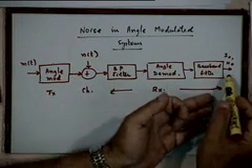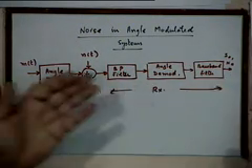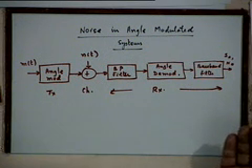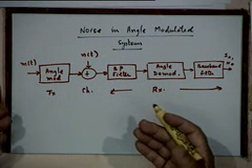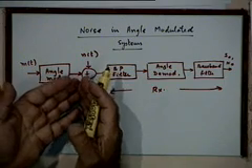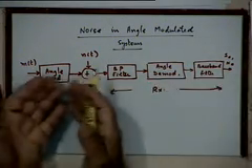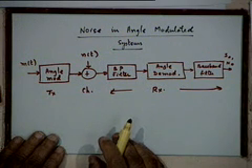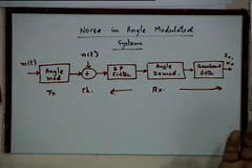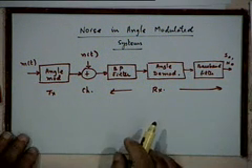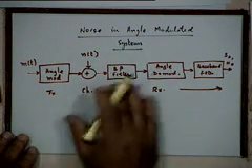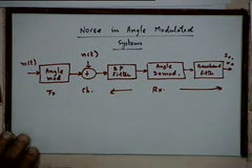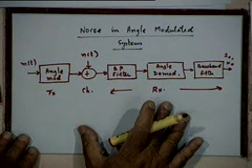That is, we assume that if I calculate the effect of signal at the output and the effect of noise at the output, I can do that separately, independent of each other. I can calculate, okay, this is the input signal power, what is the output signal power? If this is the input noise power, what is the output noise power, and then take the ratio, right. Linearity implies that the ratio will be just the same, right. I can't do that anymore. It's not a linear system. So, these are the two complications that we have to take care of in the analysis of angle modulated systems.